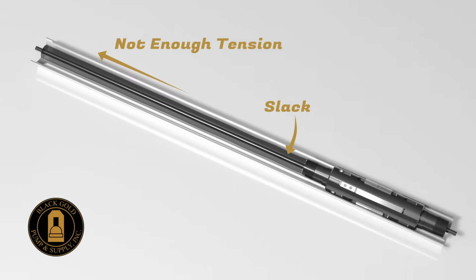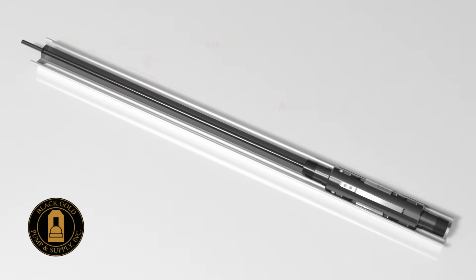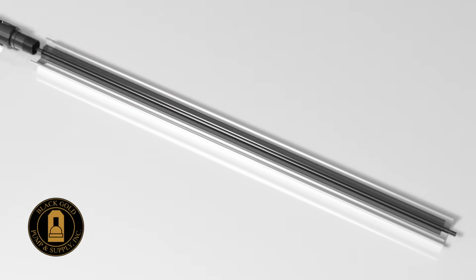turning at the anchor. Once the slips have fully engaged, the tubing can be stretched to the calculated number of inches in order to account for the fluid load change from static to producing. The goal here is to pull just enough into the tubing that when everything settles out, the tubing tension just above the anchor is slightly positive. We must make sure that slack doesn't deflect the tubing into the rods as gravity pulls it down. But what if there was a better way?